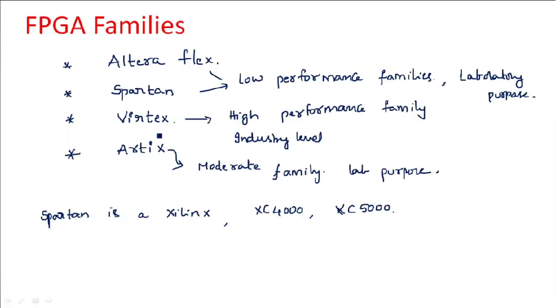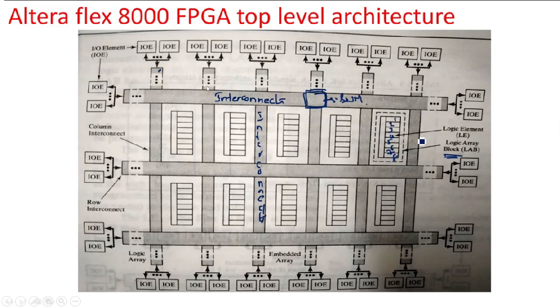See here, the Ultraflex 8000 FPGA top architecture family. It consists of IO elements, which are IO blocks, and interconnects. Here the CLBs are logic elements. We call them logic elements, or logic array blocks, labs.